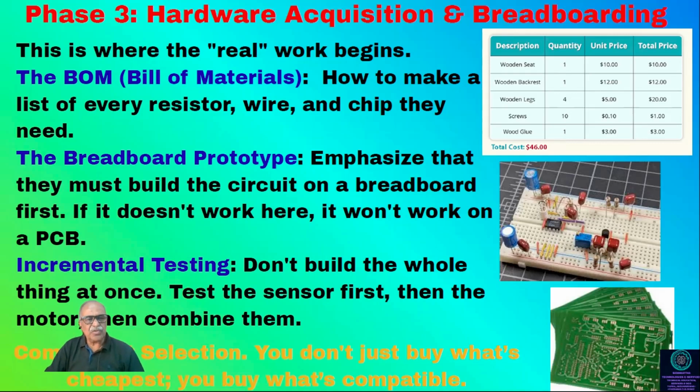Anyhow, so incremental testing, that is, don't build the whole thing at once. You have to make it stage wise. First the power supply stage, then another stage, then another stage. Likewise, you go on, so it will be easy. Don't spread out the whole thing together. Right? So that is the meaning.